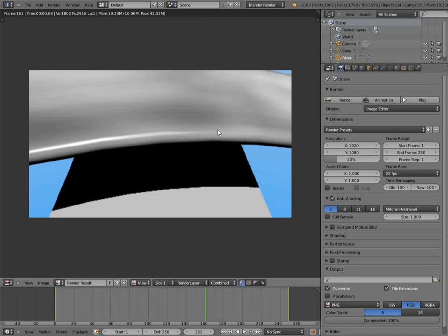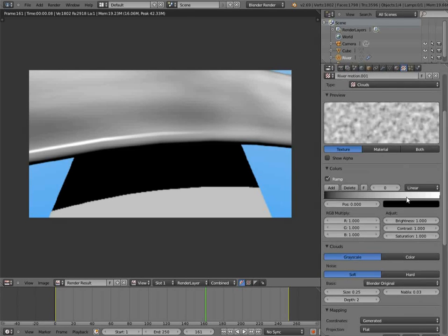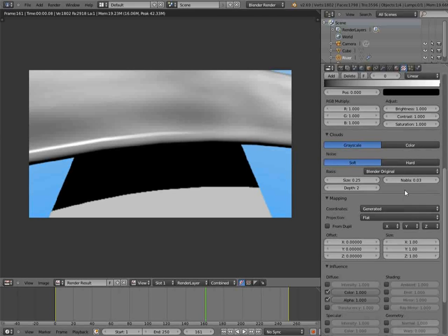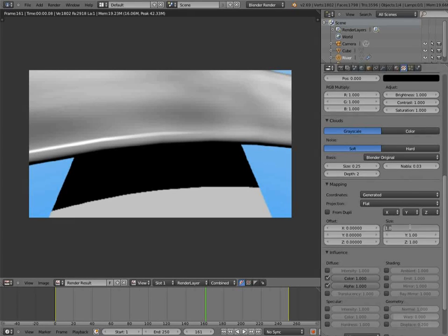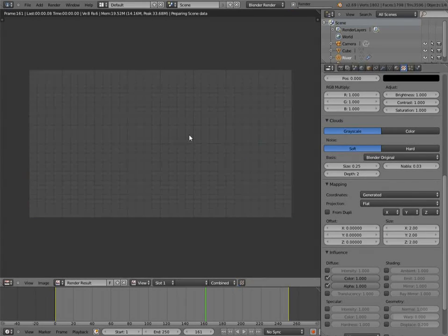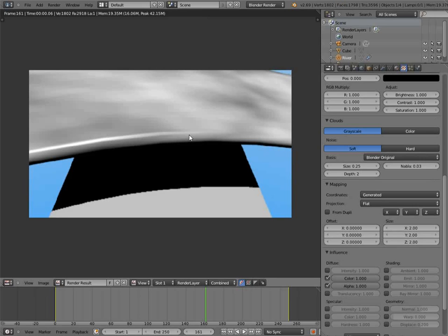there we go. Okay, now we have a rough idea of where the texture will be, because these thick spots over here are from the new texture. If you use those thick spots and you make them a bit smaller, let's say we make this 2 all around, see it render again. Yeah, that should make a good impression. Okay, ticking off alpha, adding normal. Let's see what it looks like. See, now we have the edges we want.